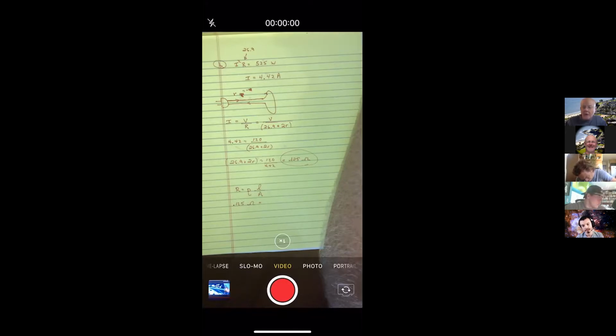Okay, maybe I need to make my screen a little bit bigger so I can see it. Okay, there's table 1. There's table 2. Okay, and so if I look up the resistivity of copper, I've got a 1.7 times 10 to the negative, make that bigger. Why does this thing default to 50%? Yeah, 10 to the minus 8, good. And then the length of it, I believe they said this was a 15-meter long extension cord. It's about 50 feet. Yeah. Okay, so that's 15 meters.